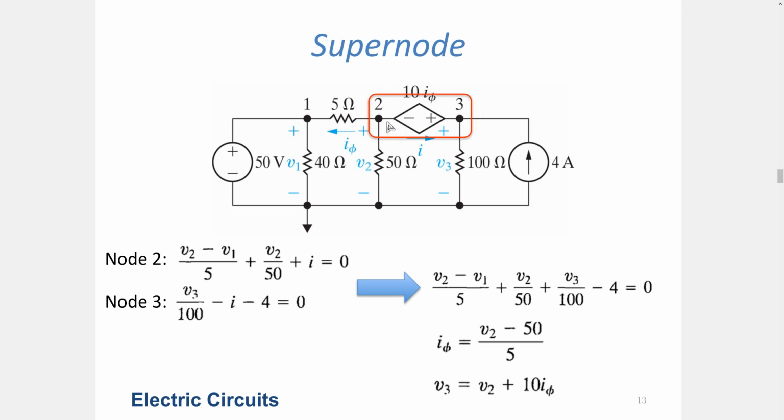Okay. So if we establish the circuit equation at node 2, using the node voltages approach, the current directions and the voltage directions have been determined. We can see that the current through the 5 ohms resistor can be defined as (V2 minus V1) divided by 5 ohms.